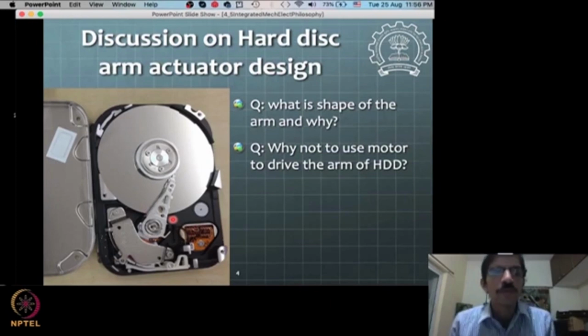Okay, that is only when we are talking about the centrifugal acceleration force. And then because of this tangential acceleration of the mass which is moving, we'll have some kind of a torque that is created here. Okay, so those kinds of forces are going to come on the arm, and one can think about and make sure that the arm is sturdy. The arm should not give way to these forces and first of all fail in stress.